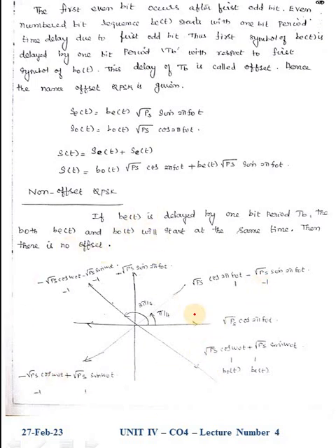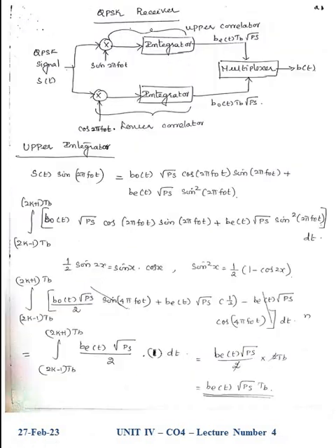So this is the signal representation, as I told earlier: 45 degree, then 135 degree, then our next phase should occur at 225, then 315 degree. So according to the symbol duration, 0 0, 1 0, 0 1 and 1 1 case, the corresponding signal levels are represented here according to this equation.